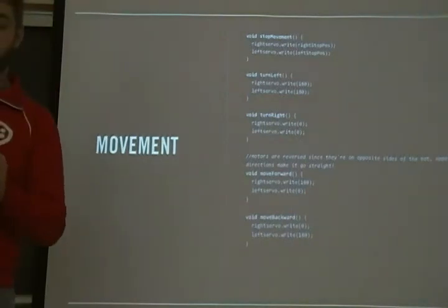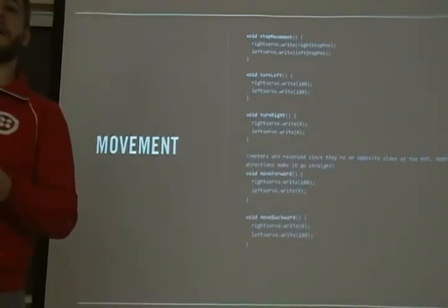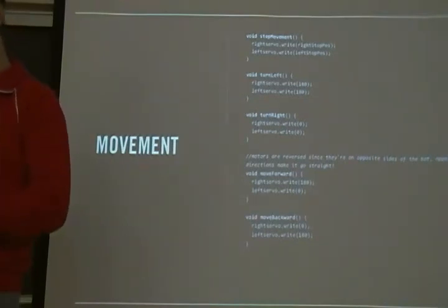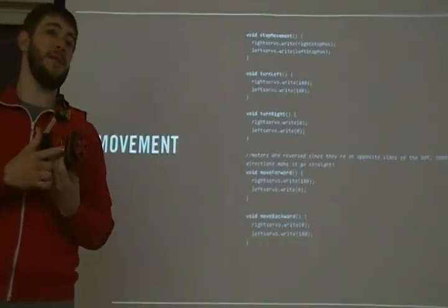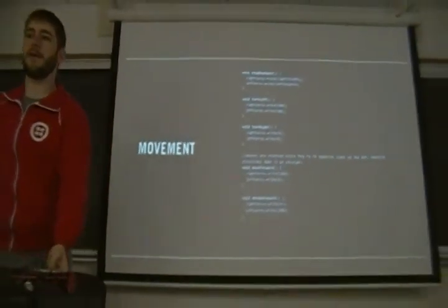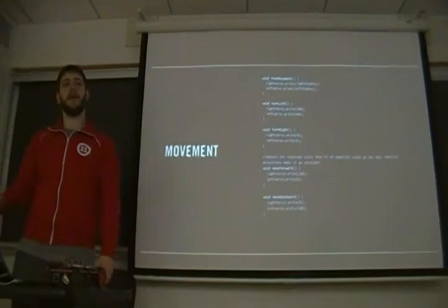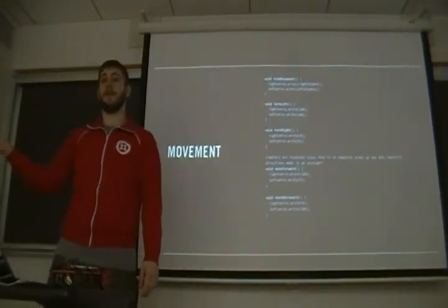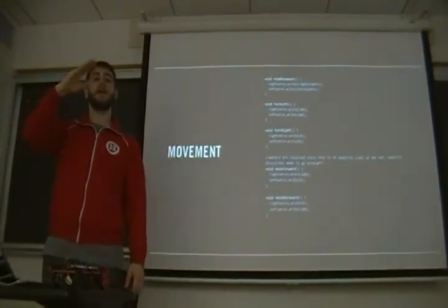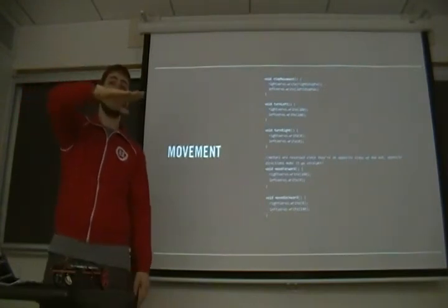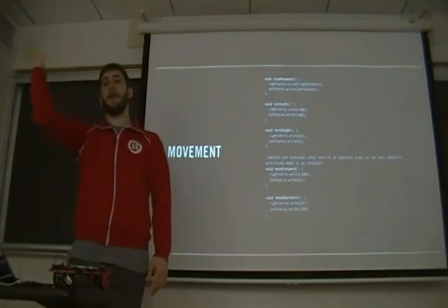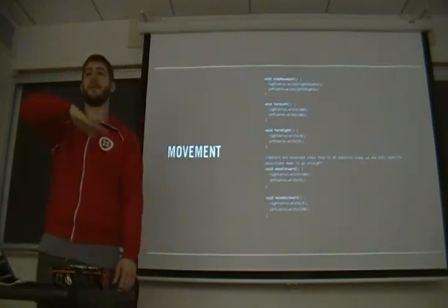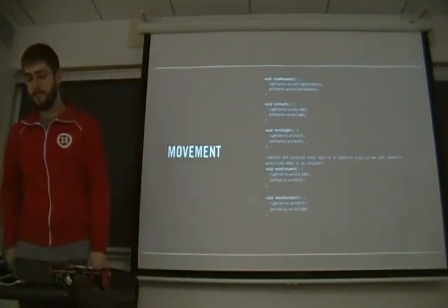but it's kind of useless for robots. So someone somewhere figured out how to modify a servo so that it can be used as an actual driver. The two servos I'm using here are modified for what's called continuous rotation, which means that there's a gear taken out somewhere that allows it to spin essentially forever. So when I tell it to go to 0, which is position 0, it'll just keep moving in that direction forever. If I tell it to go to 180, it'll keep moving in that direction forever. It doesn't just stop at either side.